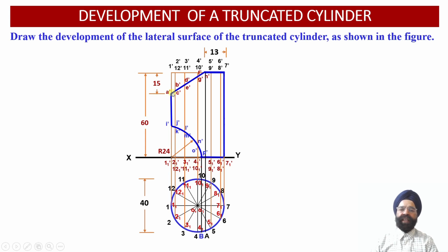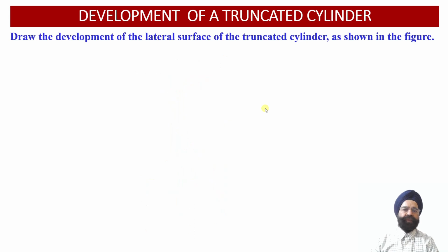Similarly, there is another cutting plane which is lying at the left top portion of the cylinder. We have been provided with the orientation of this auxiliary inclined plane, or the second cutting plane, as shown in this figure. So we have two cutting planes which are going to intersect with this right cylinder. Now let us proceed with the construction of the orthographic projections of the cylinder.